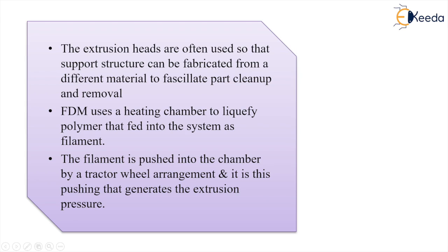Then this filament is pushed into the chamber by a tractor wheel arrangement, and it is this pushing that generates the extrusion pressure, whereas in real extrusion the ram creates that pressure.